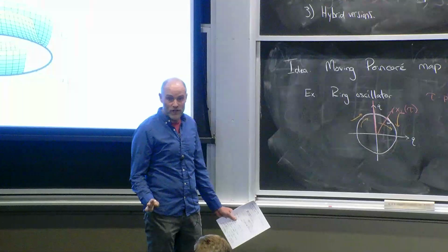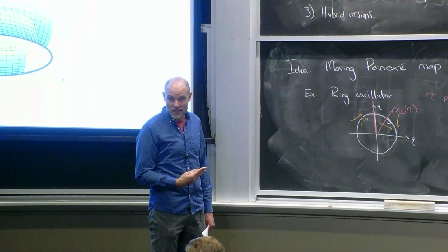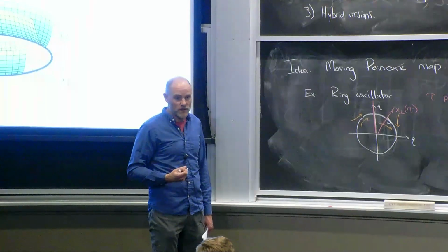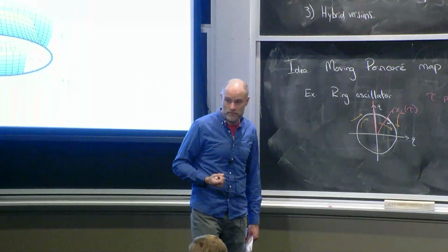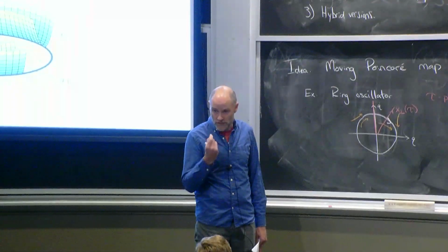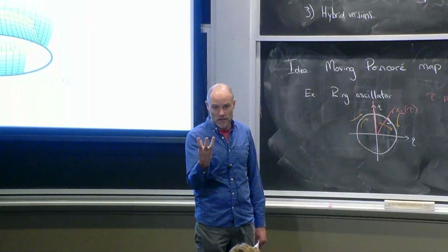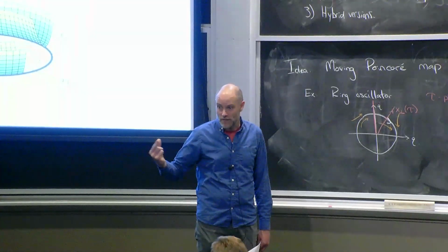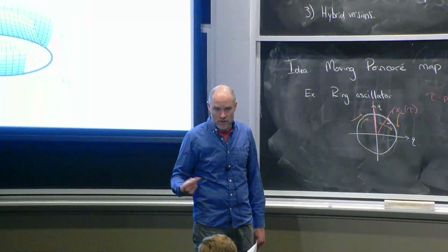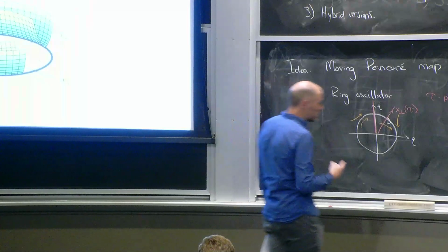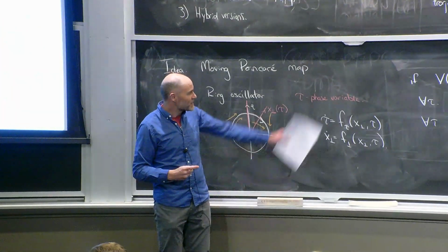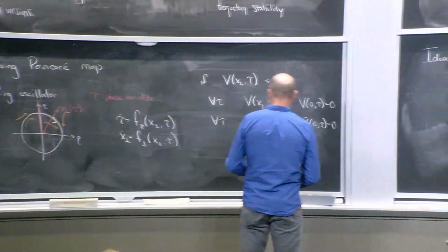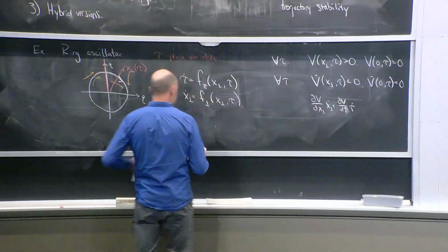You might ask, how do you find a Lyapunov function like that? How did we find Lyapunov functions in the fixed point case? We did sums of squares ultimately, but how do we get an initial guess for sums of squares? Take the Lyapunov candidate as linear. Exactly. You can take the linearization around a fixed point and compute the Lyapunov candidate. In the trajectory sense, we did that again. We said you could take a time-varying linearization, and you could get a time-varying Lyapunov candidate by solving the time-varying Lyapunov equation. Guess what? You can do the time-varying version of this, the time-varying linearization of this, but now it's not explicitly varying in time. It's a function of tau. So we're going to call this the transverse linearization. I'll start here.